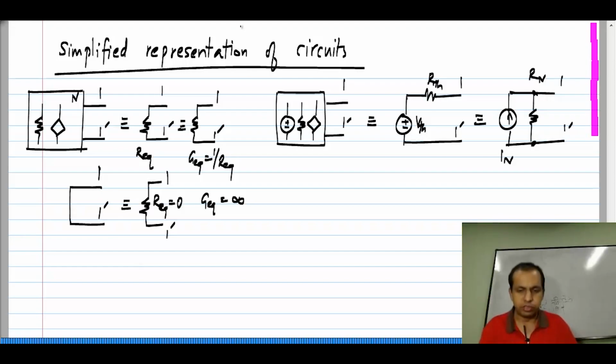So, when you have a short circuit, saying that resistance is 0 is a legitimate representation, you can use this in calculations. It is correct to say that the conductance is infinity, but you can't use this number in any useful calculation. So, this is a very simple example of why specifying resistance or conductance can be useful, and also you can see why in this particular case only one of them has a finite value.